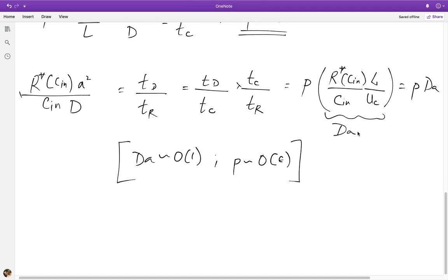So we can't have a problem where the Damkohler number is extremely large, nor a problem where the Damkohler number is extremely small, because otherwise the reaction rate term will again become insignificant, and we'll have to change the way we are balancing the problem. Or at the very least, the reaction rate term will come in as a much smaller effect.